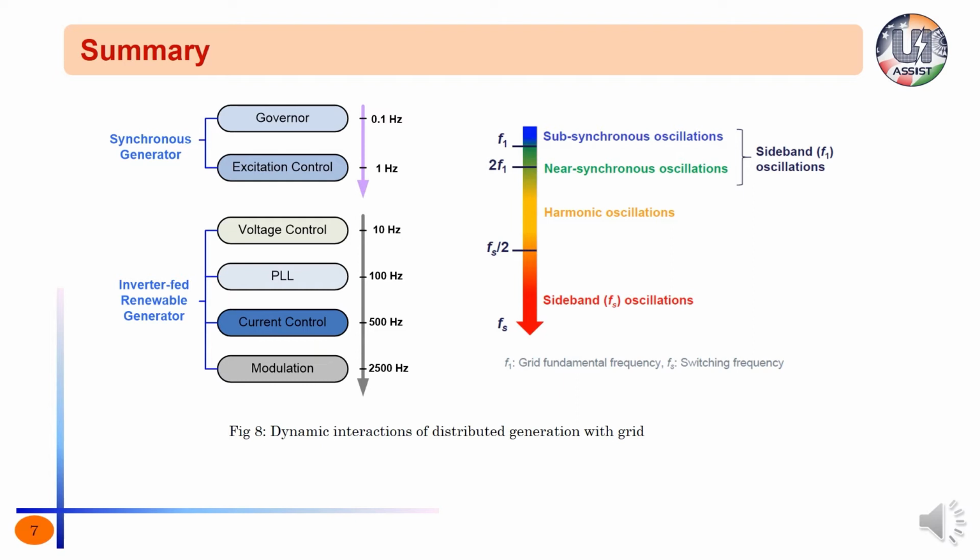Ultimately, the characteristics of these control loops in an inverter shape the overall output impedance or admittance of the inverter. To be more precise, these control loops have a larger impact on damping characteristics of inverter output impedance within their bandwidth range. As a result, outer loops may initiate harmonic instability or even resonance in the low frequency region. Similarly, the inner loops in the high frequency region.